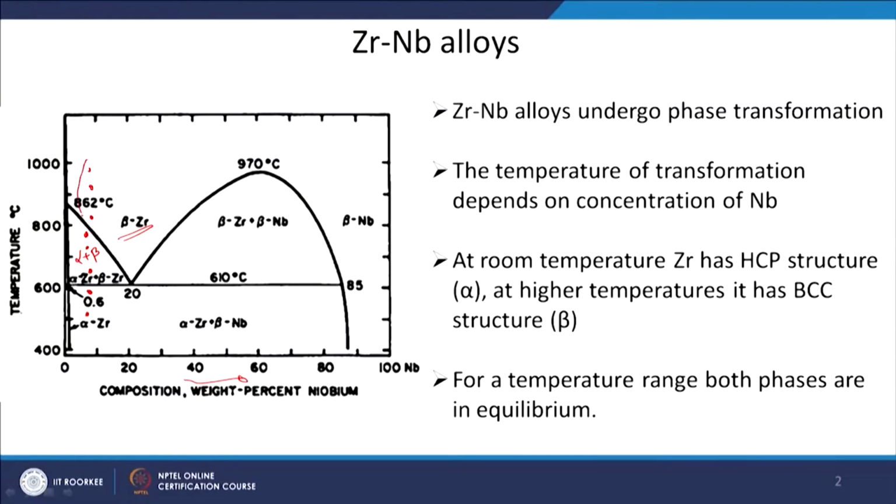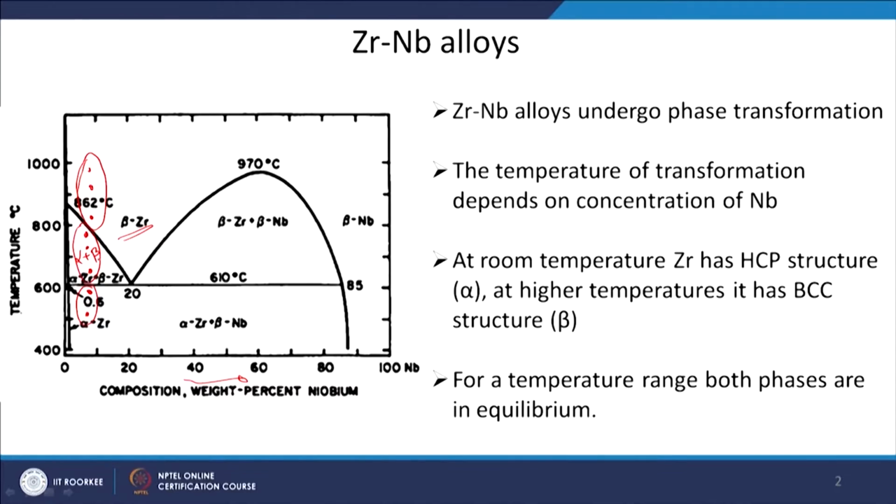So, we propose that we should develop constitutive equations based on the phases present: one constitutive equation for beta phase, one for the alpha plus beta two phase region, and one for alpha phase. So, independent phases. Incidentally, most of the processing for these alloys takes place in the two phase region, so this region is important for processing.